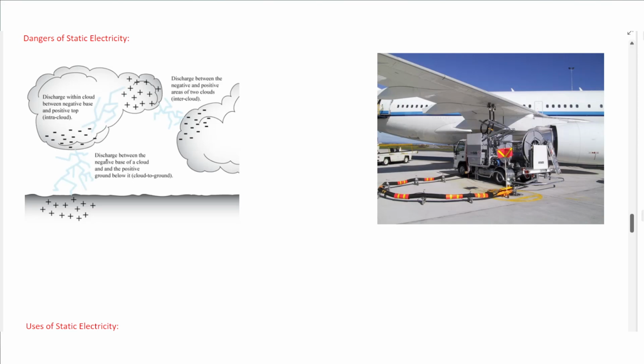or in the case of an airplane, the charge will be much greater since the body of the plane can carry much more charge. So at first, before fueling a vehicle or a plane, you must earth it to remove the charge to avoid the sparks happening during the flow of fuel, because fuel is flammable and any spark will ignite the fuel and cause it to catch fire.